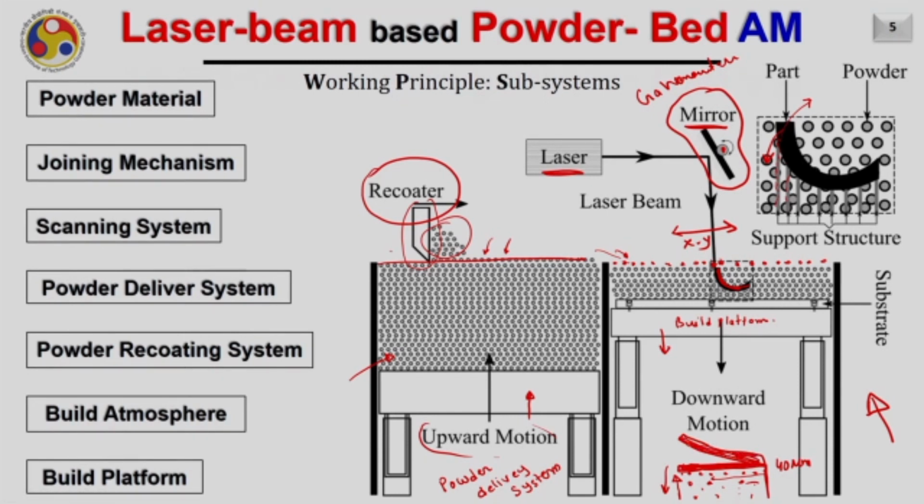And if the layer gets warped, we know that this recoater may hit it and there may be chances of not being able to complete the part efficiently. Therefore, usually if the material used here is prone to deflection, it is prevented by providing appropriate support so that it does not allow this layer to warp up and keeps it straight while depositing the large overhangs.